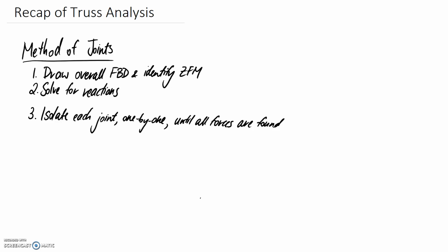Once you've done that, you should be able to identify any zero force members if you have them, and I'll go through in a little bit more detail further along in this video about identifying those zero force members. So the next step that you can take is to solve for reaction forces. However, I have to note that this is not always necessary. It's dependent on what your structure actually looks like and where the supports are located. So yeah, it's very question specific as to whether you actually need to do this.